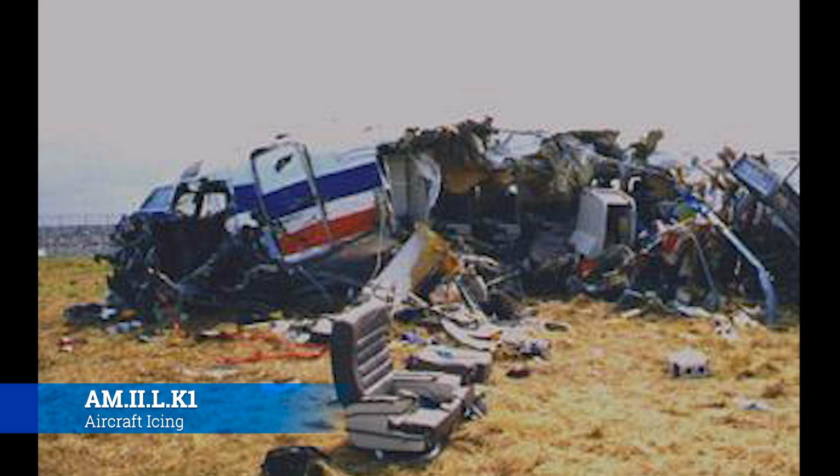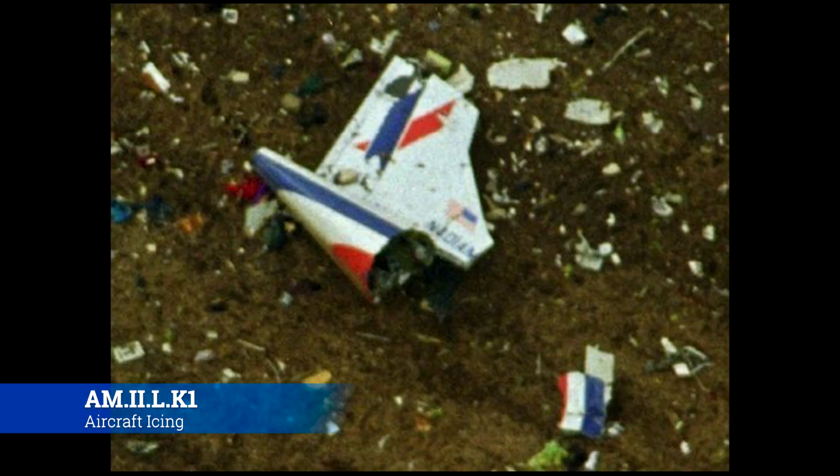However, they had also dropped the flaps to slow down while in this holding pattern. As the flaps came down, it caused the wing to pitch up slightly, and as it pitched up, it created just enough surface area behind the boot for the ice to continue to build up. So this ice builds up, and whenever the airplane starts to sink because it's not producing enough lift, the airspeed starts to come up.